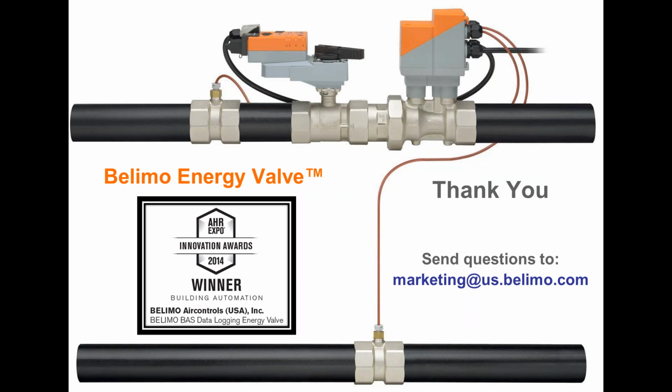That's the simplified explanation. So the Belimo Energy Valve communicates in a bunch of different ways. It has an analog output feedback like a standard actuator. It's also a BACnet capable device, and through any of those types of communication you can receive valve position, and that will allow for the employment of that strategy.